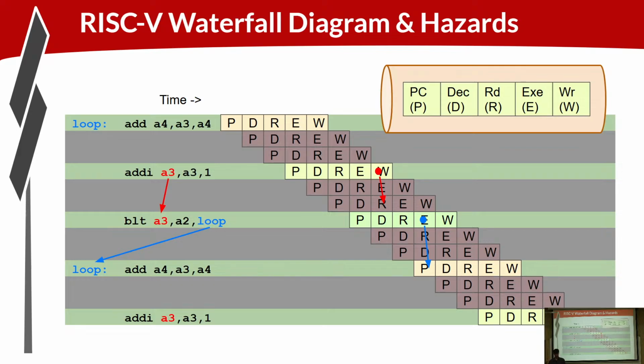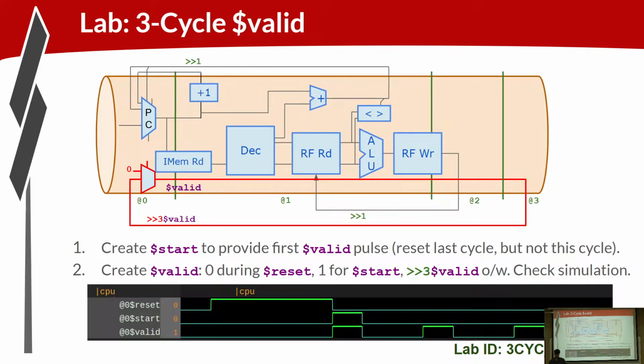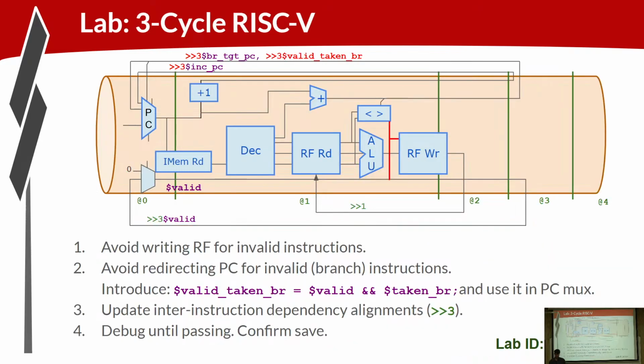With that cadence set up and the execution of the CPU every 3rd cycle, we added the logic that would deal with the hazards so that we were ready to execute instructions back to back. To add that logic, first we set up the 3-cycle cadence, made sure that the PC update was a 3-cycle loop.